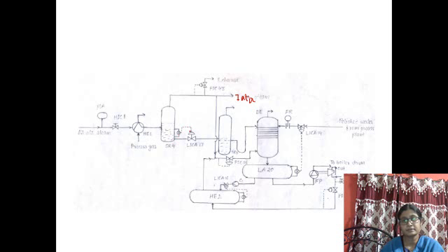So this is the symbol for a level controller. Here no controller or other devices have been shown. This is the PI diagram. It may be shown that there exists the controller, or may not be, depending on the space on the diagram page, but it stands for the level control system, level controller along with alarm facility and indicator for monitoring.